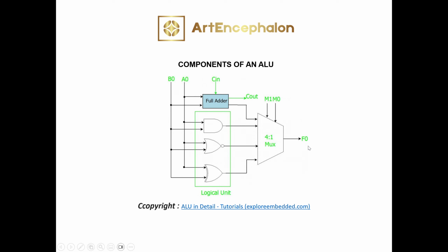So for example, if I just want to do an ANDing of the 2 bits, and that's usually for comparison. Maybe I want to find out if bit A and bit B are the same or if they are different. If I want them to be different, for example, then I would say anytime they are the same, it should be 0. When they are different, it should be 1. So in such a case, you use an exclusive OR gate.